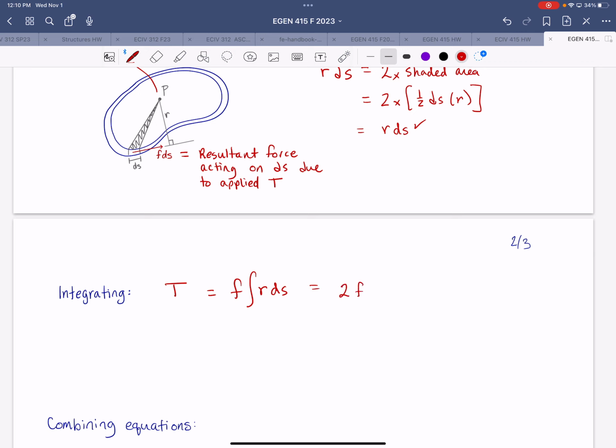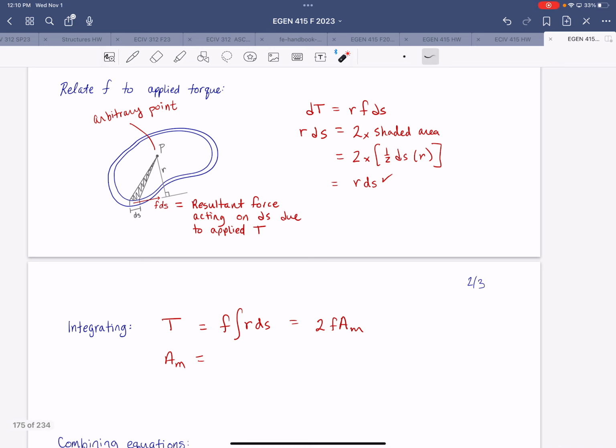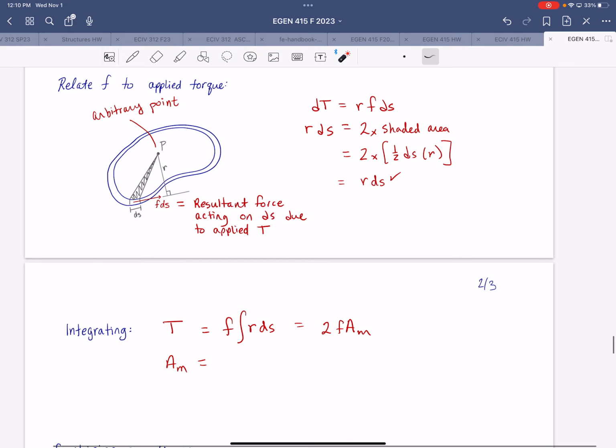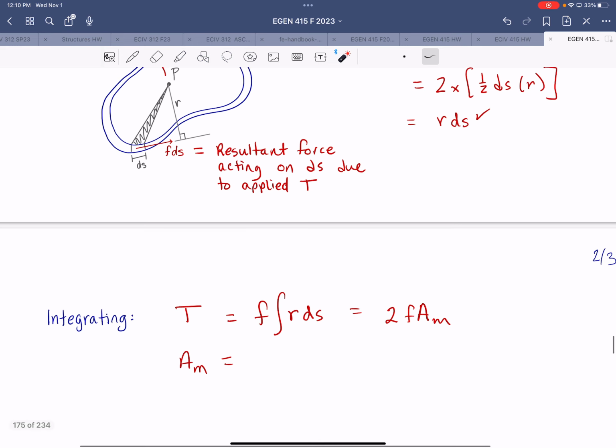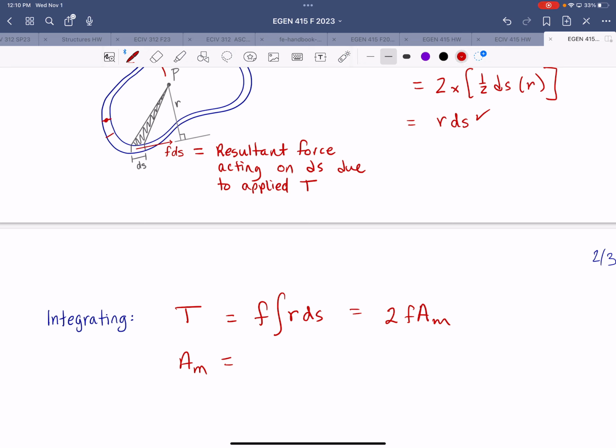And I will define that term right now. So A_m represents the solid area that is enclosed by the median center line of the circumference of the cross section. So the m stands for median. If you imagine within this element, identifying the median point at any given location and then figuring out what that line is, everything within that line, that circumference will enclose an area.